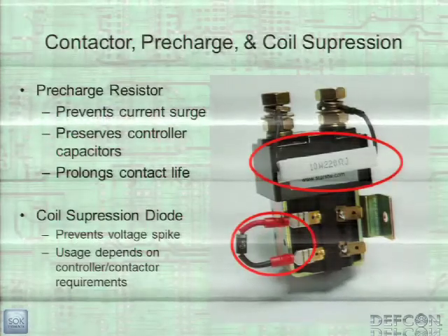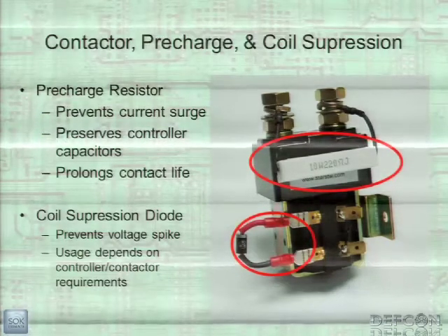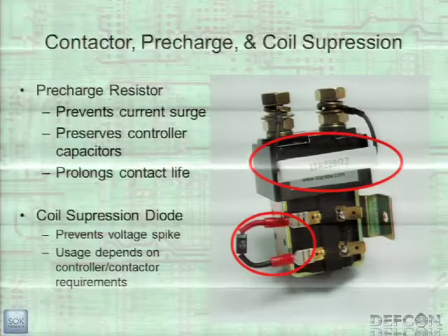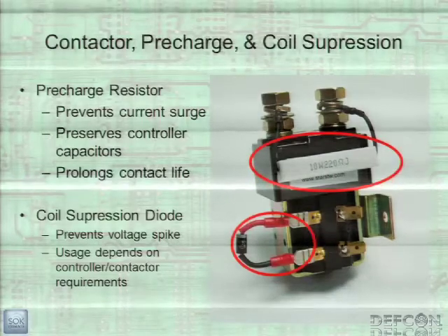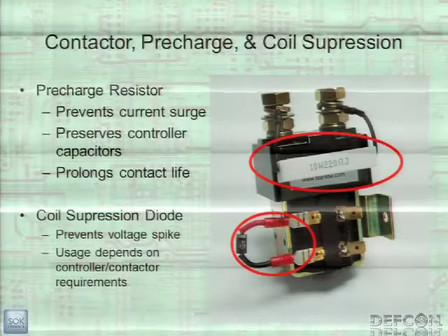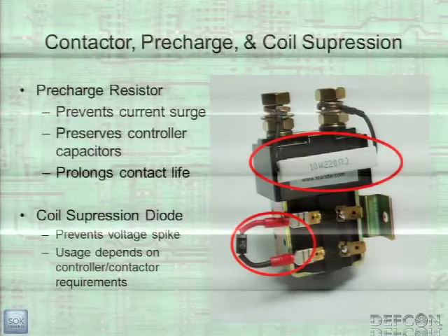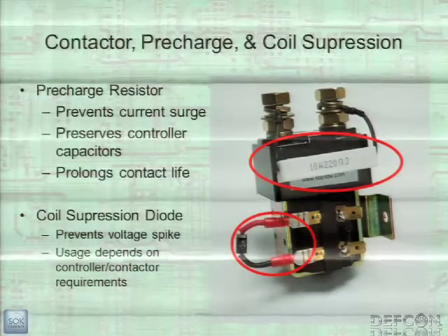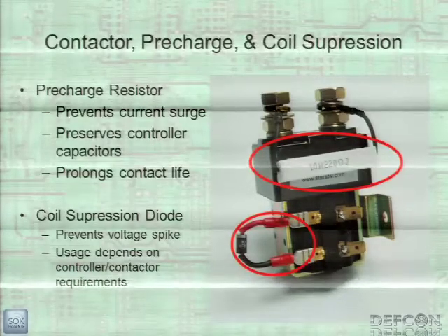An important thing to know about, and a common question that newbies have, is what's a precharge? Your contactor is a really big relay that's designed to handle the hundreds of volts that you're pushing through your electric vehicle. Your motor controller is full of large capacitors, and when they're empty and you turn on your relay and push the volts through it, your voltage differential is large, so the current goes to infinity. Obviously, infinity is a bad current to have in your motor controller.